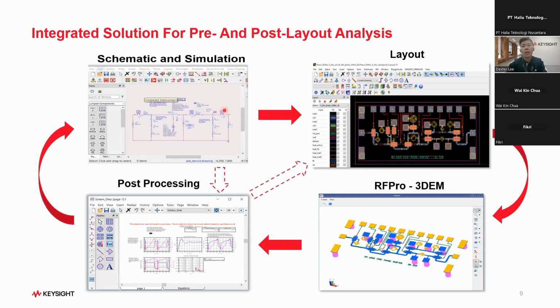The next step is to start moving into layout. So we have the feature called the design synchronization, which can help you to move everything that you have designed in schematic to the layout portion and do your layout design. Okay, so this is the layout design. And once you have finished your layout design, you can start to do the EM simulation. So today's main highlight again is on RF Pro. It gives you a 3D view and lets you quickly do your EM simulation setup here.